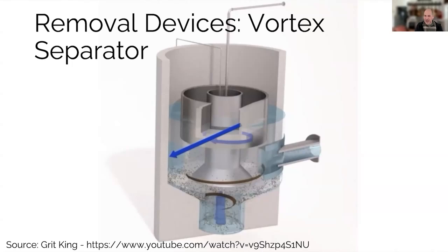They also typically have very low head loss and a small footprint, much smaller than a settling basin. So as plants are being designed, obviously space is a concern. So you might have a vortex system set up because there just isn't room for an aerated grit chamber, which tend to be very, very large. The downside of these, of course, is that they can get clogs in the grit sumps, which are down at the bottom, so it makes them a little hard to clean and work on.